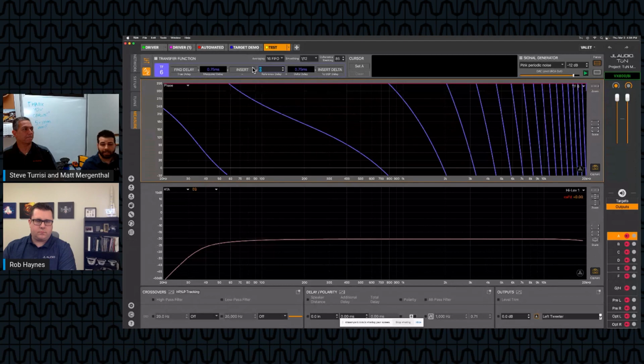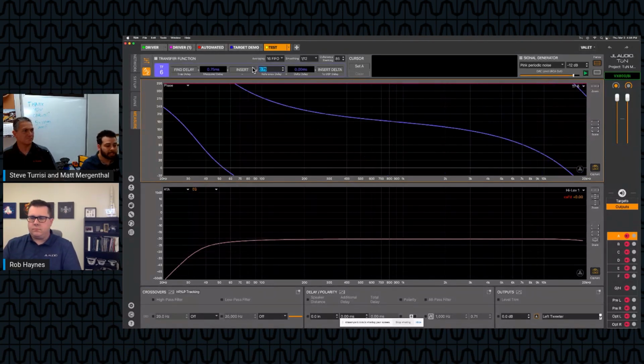So the phase plot that you see now looks different than it did a moment ago because we didn't have that reference. Without that reference delay, and once you get good at this, you can look at that and say, something's wrong. You see something like this, and you say, that makes sense. It's a nice, smooth, and continuous thing without a whole bunch of additional what's known as wraps or additional lines drawn on the screen as you see here. So, yep. Having 0 in there obviously makes it very hard to see. So we're going to put our reference delay back in, and now what we're seeing is a couple of things.